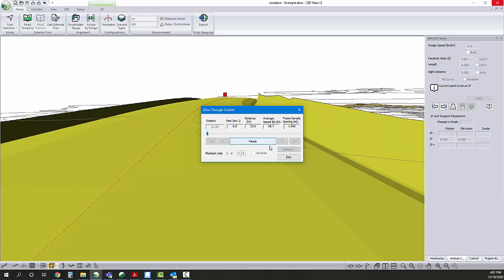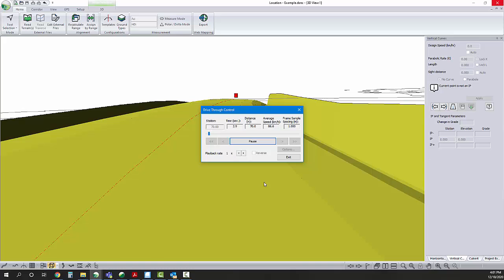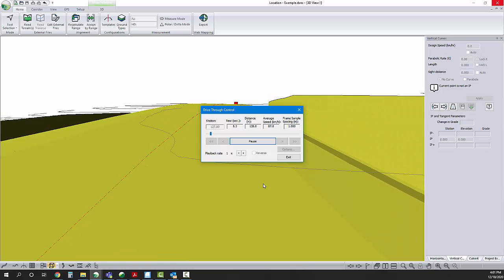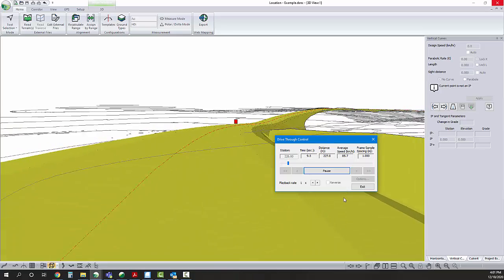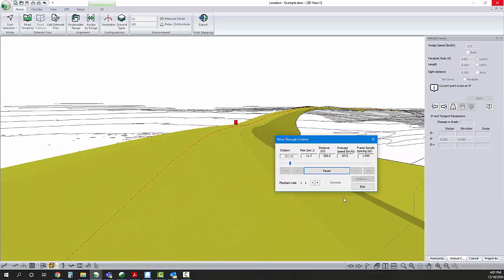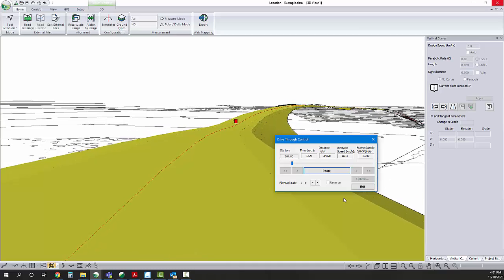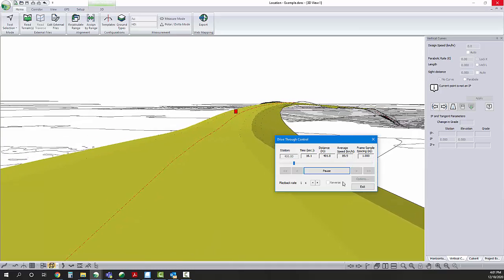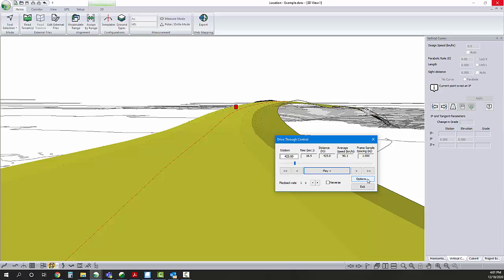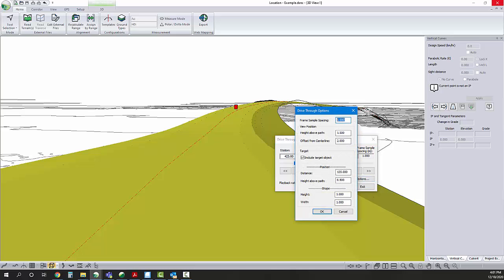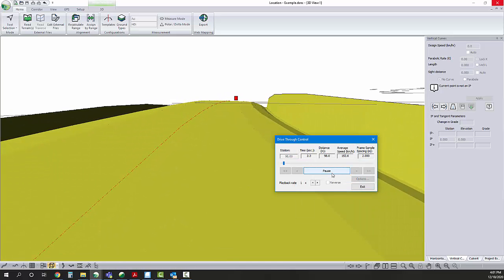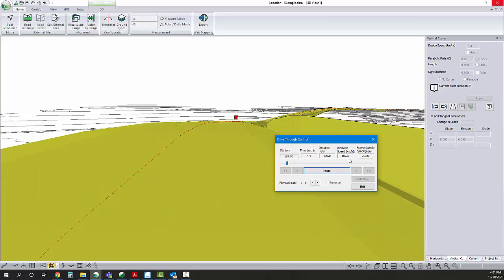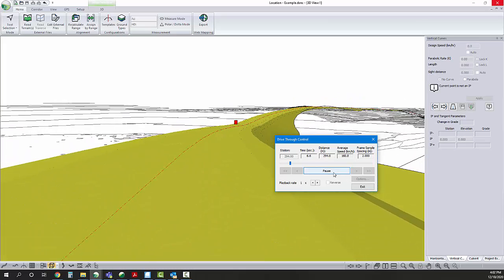We'll hit play and move this to make it easier to see. Which is great. Now, if we want to speed things up, we can change the frame sample spacing. Go 2 meters instead of 1. We're going a bit faster. It's giving us our average speed over here.